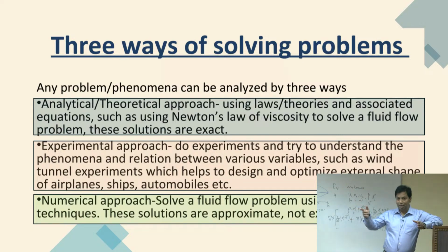For example, we have the unsteady term, the advection term, the pressure gradient term, and the viscous term. During unsteady flow development, in some stages some terms are important and some terms are not. For example, very initially when t is very small, the advection term is not important because the flow has not started. Mostly conduction is the important one.